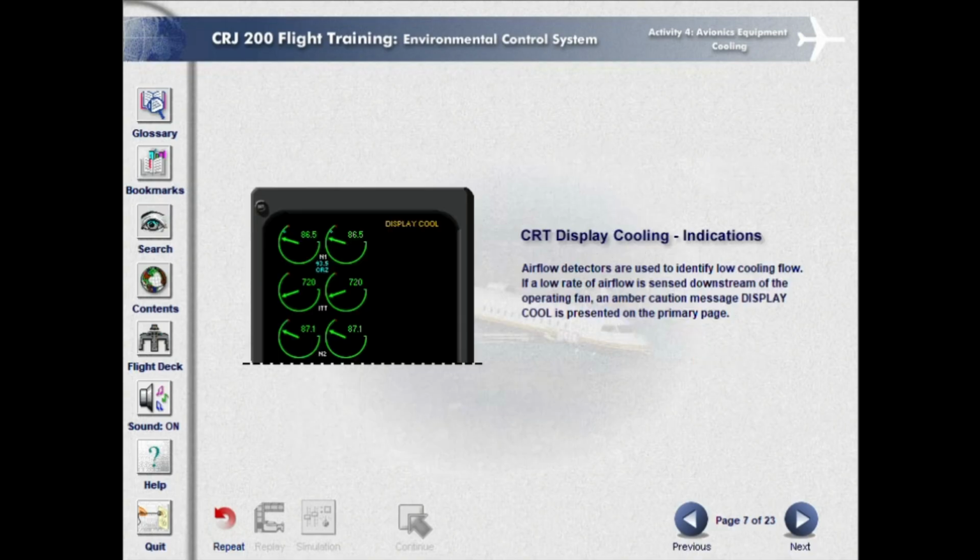CRT display cooling. Indications. Airflow detectors are used to identify low cooling flow. If a low rate of airflow is sensed downstream of the operating fan, an amber caution message display Cool is presented on the primary page.